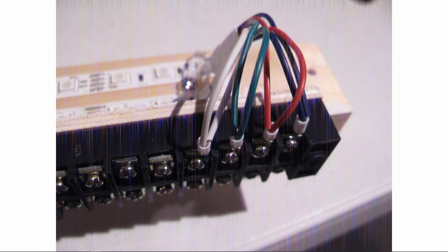The difference is that the lighting will be more even if you feed smaller sections of the LED strips. So in other words, both these LED strips are getting the exact same voltage at this end, because as you go down to the other end, as the current draw, basically you could say it's the highest at this end, so you've got the most voltage dropped over the copper, IR losses. And if you don't know much about IR losses and voltage drop, don't worry about it. Just take my word for it. The shorter the length that you apply the power to, the more even the lighting.